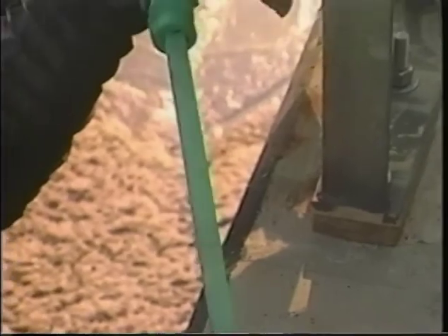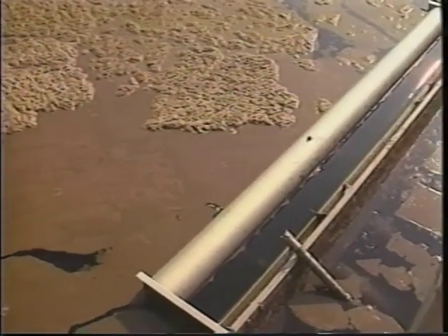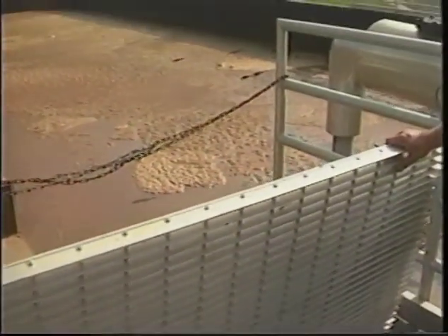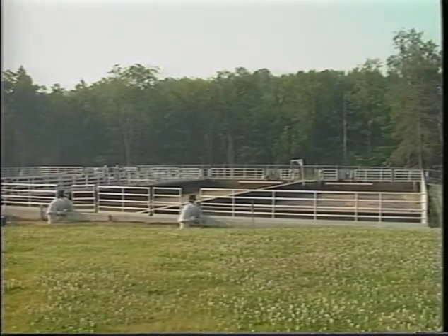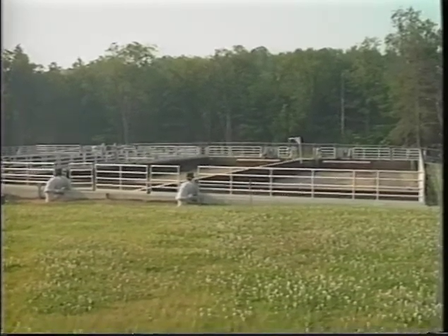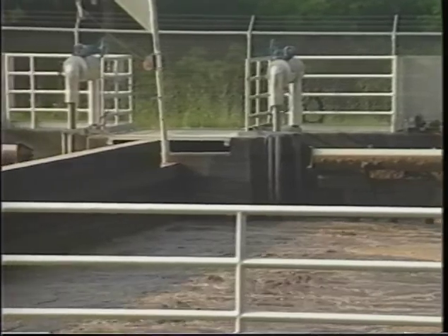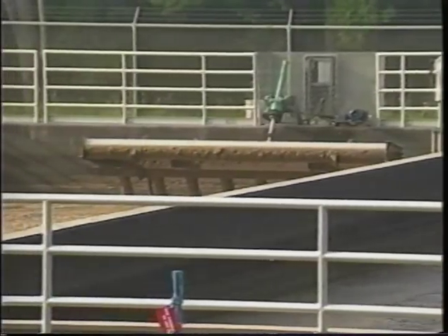The decanting mode, where some type of decanting device lowers into the tank and removes the treated wastewater from the aeration tank. Usually sludge is wasted from the tank in this mode as well. Ordinarily, the time for each sequence depends upon the incoming flow of the treatment facility and is controlled by some type of computer. While not all sequential batch plants operate exactly as described above, it gives you an idea as to the basic concepts of their operation.